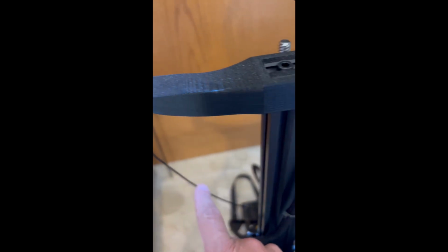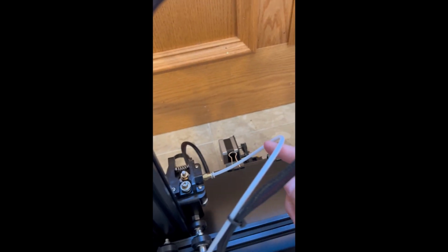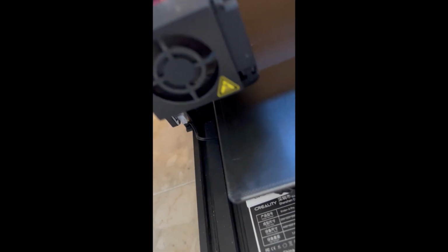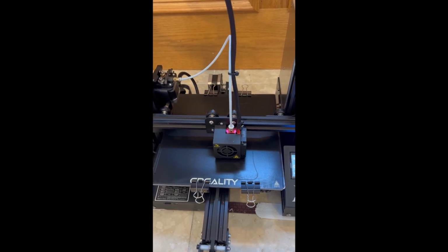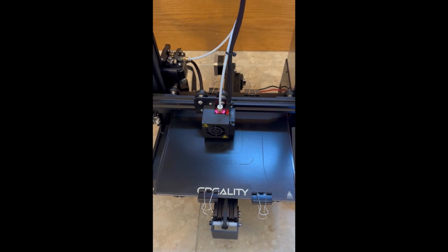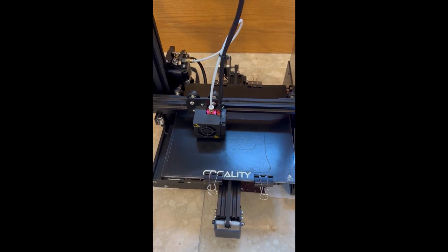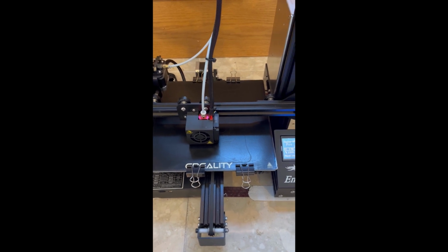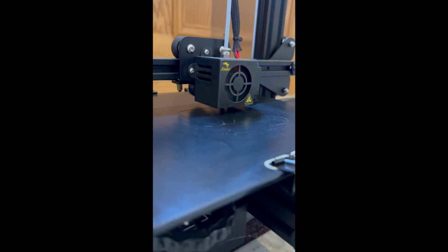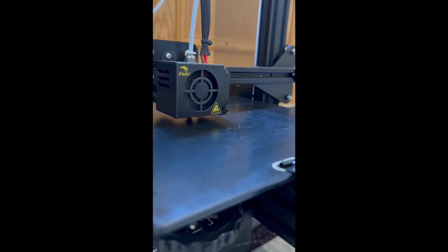And what you're looking at now is the filament. That's what actually goes through this little tube here. It gets heated in that little box right there. And then there's this little teeny tiny metal or brass extruder nozzle, and that gets very hot, about 200 degrees. So it melts that plastic filament, and then it squirts it out exactly where your slicing program told it to squirt out. And it just builds up these layers and layers and layers and layers.